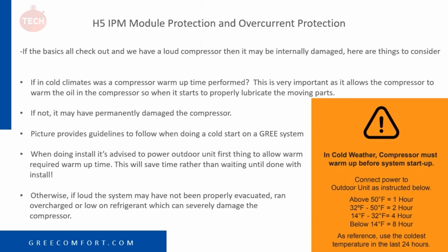If you're in cold climates and the compressor warm-up was not performed, that would definitely lead to some damage to the compressor. This is very important, as it allows the compressor to warm up the oil in the compressor, so when it starts, it properly lubricates the moving parts of the compressor. If it was not, again, it can permanently damage your compressor. The picture to the right shows proper warm-up time. Kind of gives you different parameters.